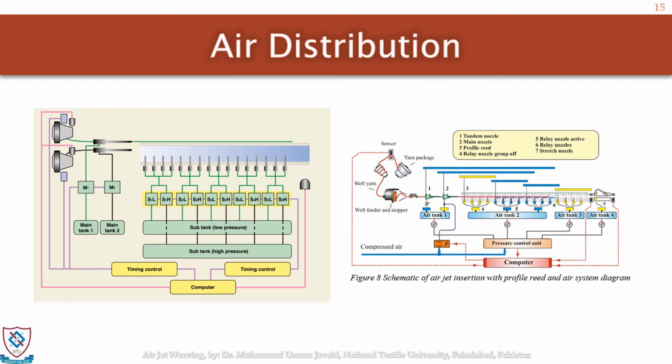You can see over here the air pressure is received from the source, generally the compressor, and then this air is distributed in the machine through different filters or some measuring device that shows how much air is being consumed, and you can see these lines distributing this air to the different tanks in the machine that accumulate this pressurized air.